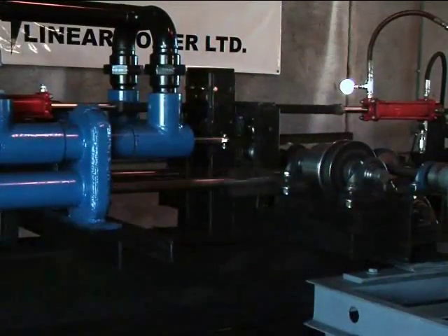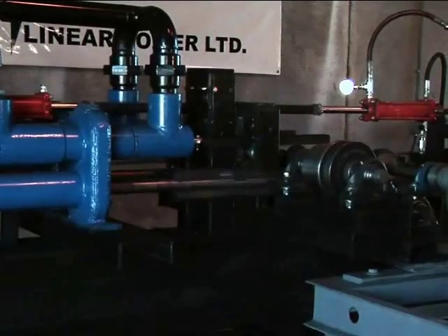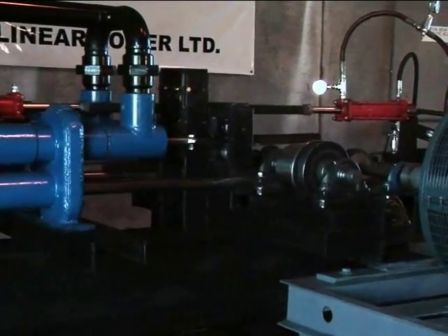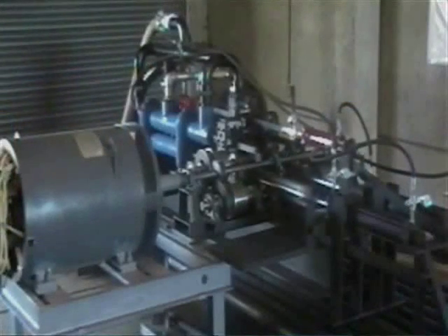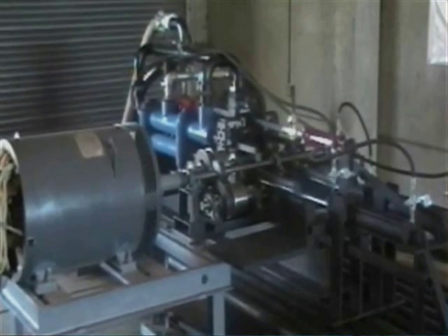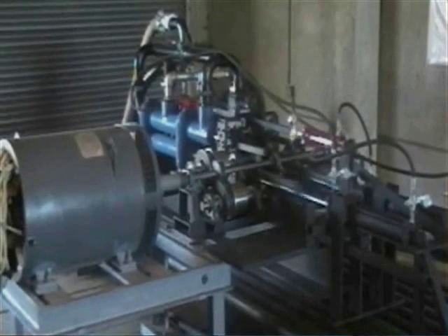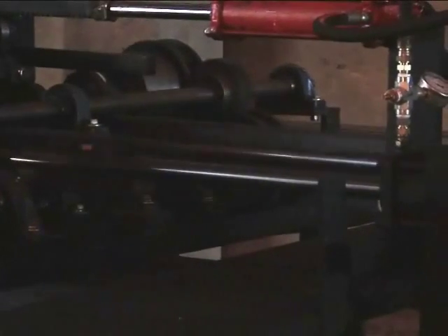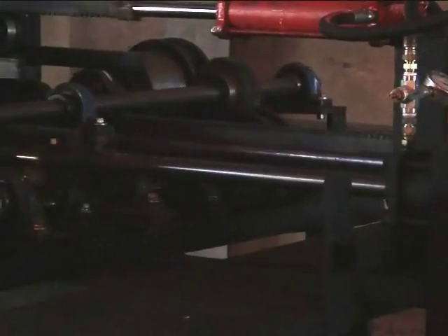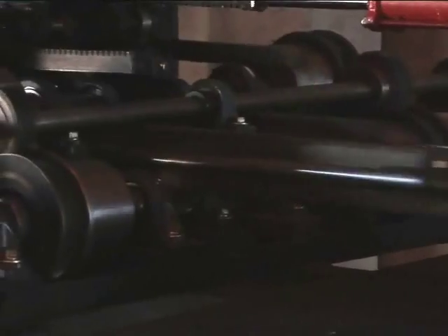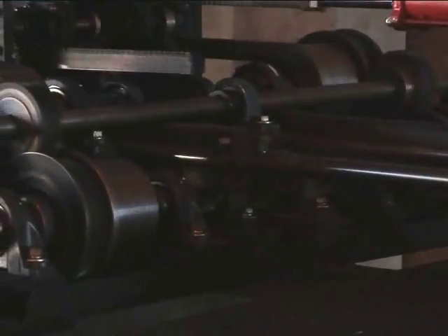Hello, I'm Robert Hunt, inventor of the world's first successful free piston engine. The term free piston means that the engine's pistons are not connected to a crankshaft like conventional engines with which you are familiar. The concept has been around for over 20 years, and early free piston engine enthusiasts envisioned smaller, lighter weight engines that eliminated poor vector angles associated with crankshafts that lose much of the power produced by the engine's pistons, with greatly reduced frictional losses.